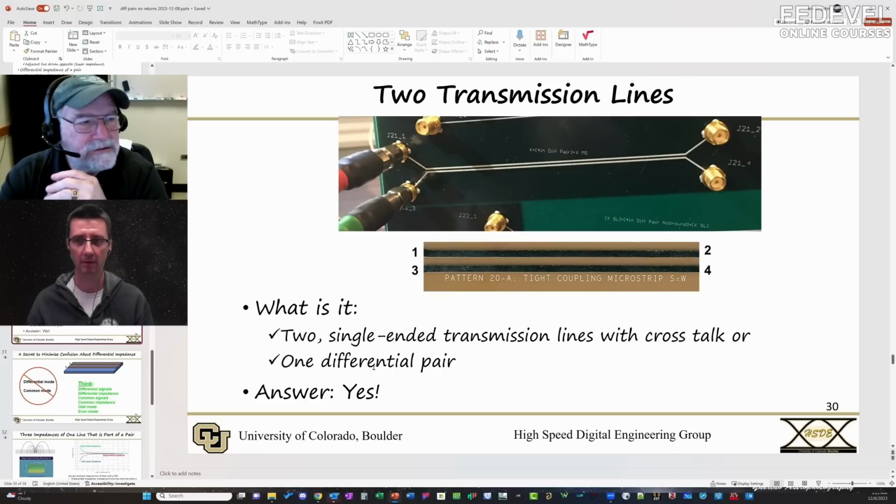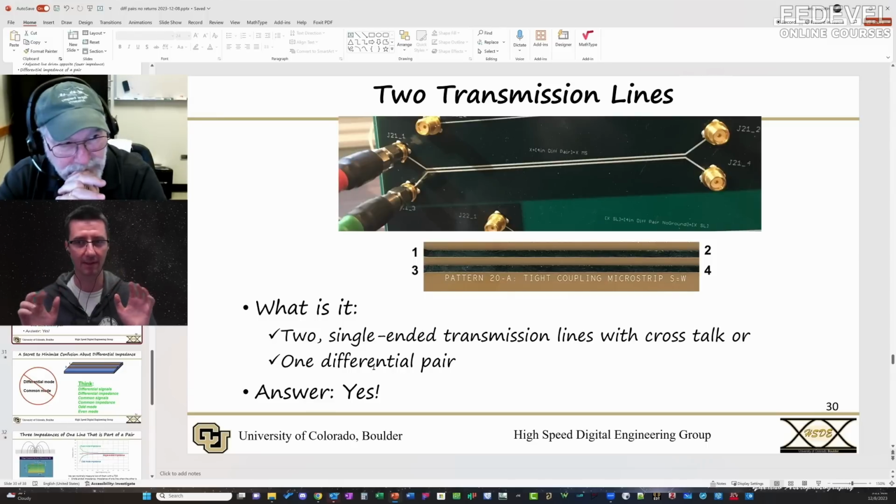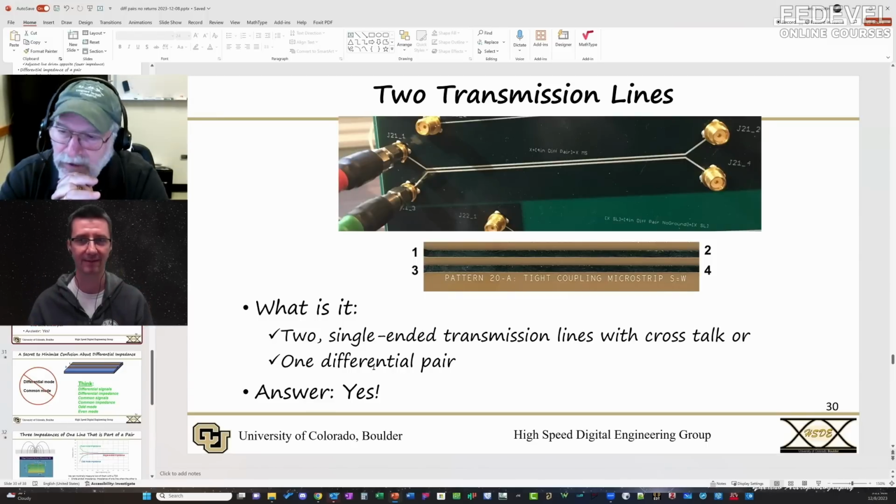It only takes about 3 microamps of common current to fail an FCC Class B test, similar to CISPR test. A tiny amount of common current. We should clarify what common means, because it means that there is some kind of DC voltage or something like this? So I wouldn't say DC, but here's what common means.